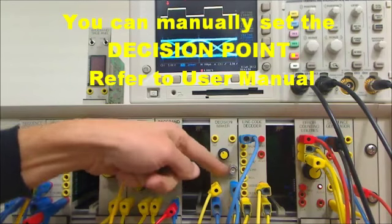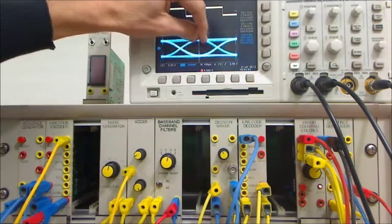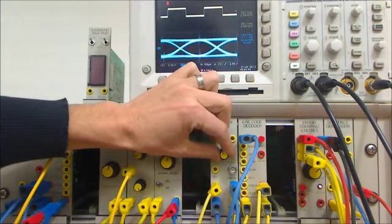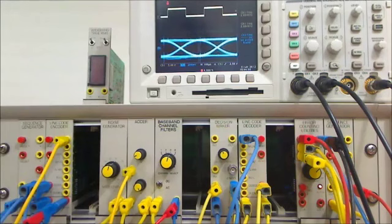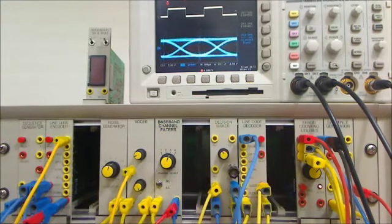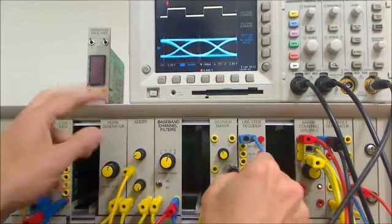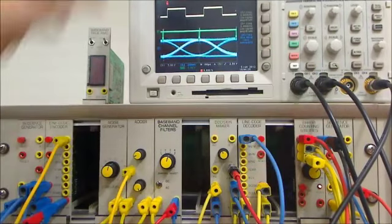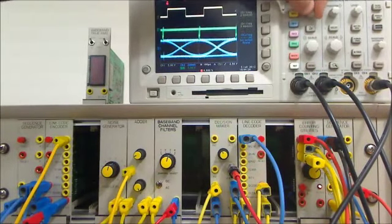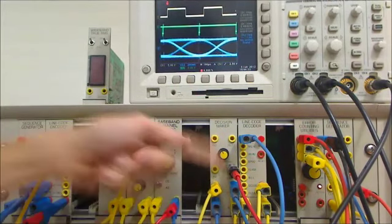There's a signal that comes out of this B and C connector. If you connect this signal to your Z modulation on your scope, you'll have a highlighted point on the eye. Another option is to view the signal simply on another channel of the scope if you happen to have multiple channels. In this case, I'll take channel 4 of the scope and have a look at the signal.